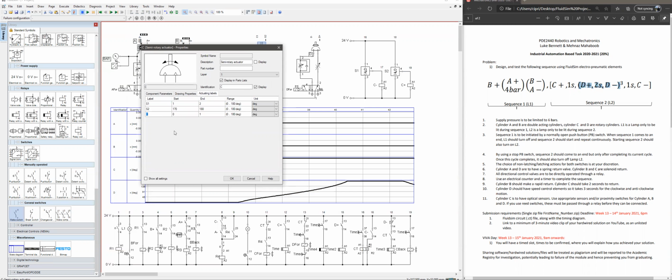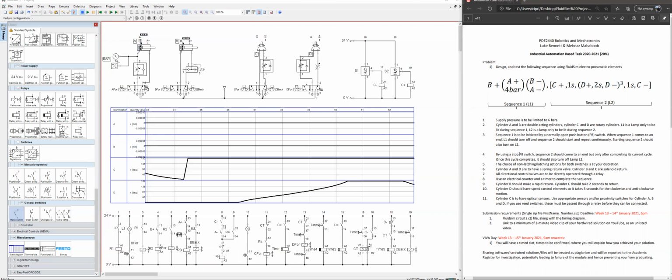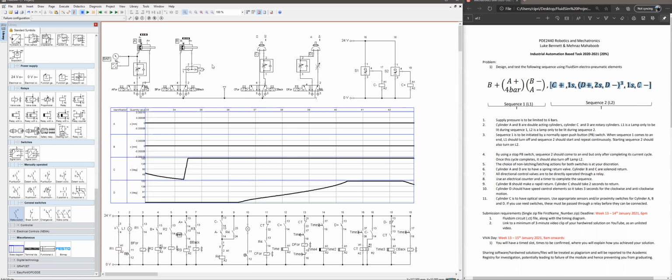And then this C label, which is being used so that the second lamp turns off only when the user has pushed the PB button, which lets the sequence come to an end only after it completes the cycle, and then it turns off the lamp. Without this label, the lamp would turn off for like half a second in between every single instance of the repeating sequence. So I'm going to have a regular one-to-one simulation here, so I can show how it works.